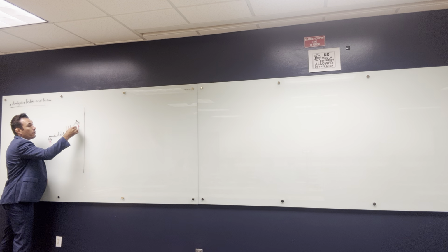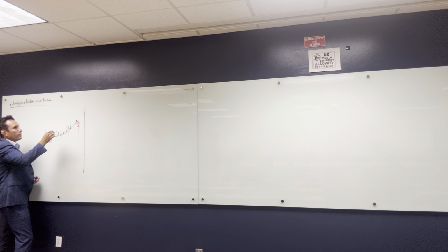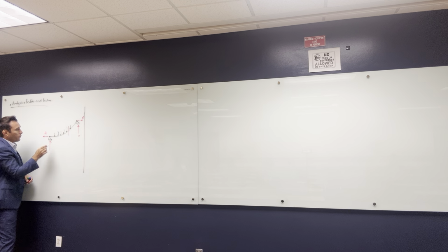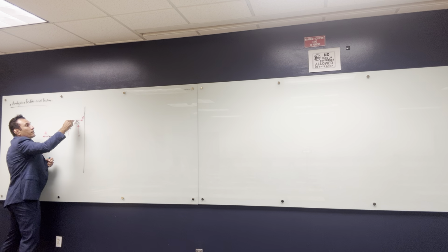If we cut this cable at any location, like here, first, to analyze any structure, you have to get reactions. Since all the loads are vertical, I'm going to have vertical reactions like this. But from the geometry of the cable, there will be horizontal reactions, because all these loads want to bring the cable down, so definitely there will be a horizontal load something like this, and a horizontal load something like this. Why? To balance the force in the cable. The cable is going down, so I'm going to have a tension in this cable going this way, so I need a reaction the other way. I have horizontal and vertical force to balance the tension in the cable. Same way here, this cable wants to pull the support down, so you need reactions on the other side to balance these forces.